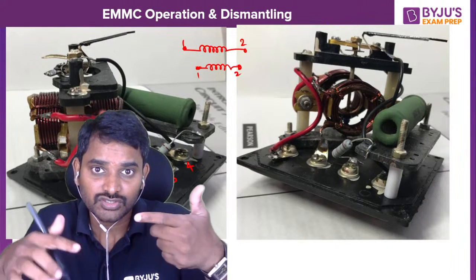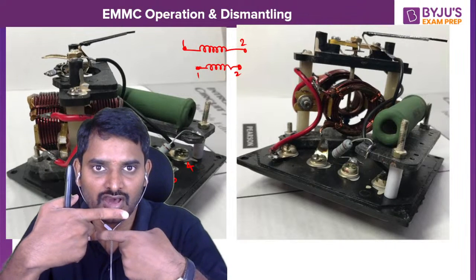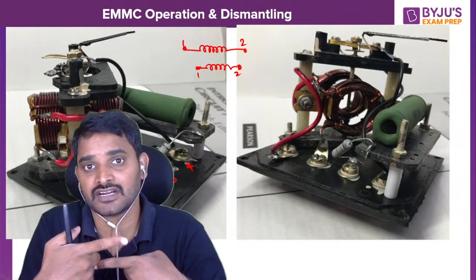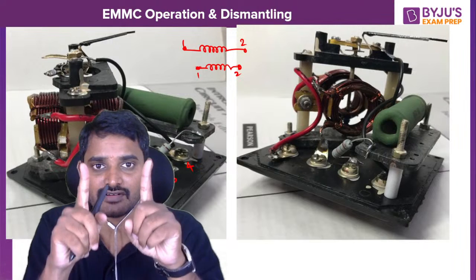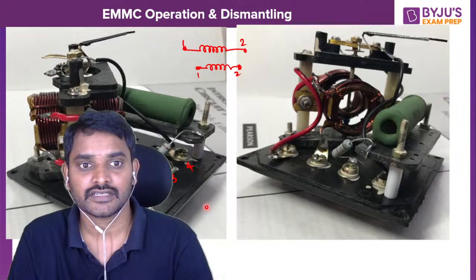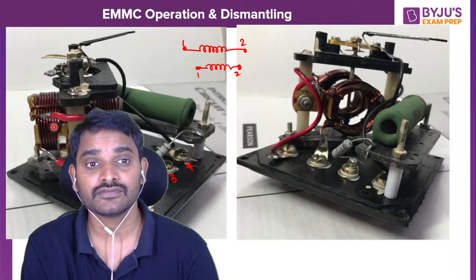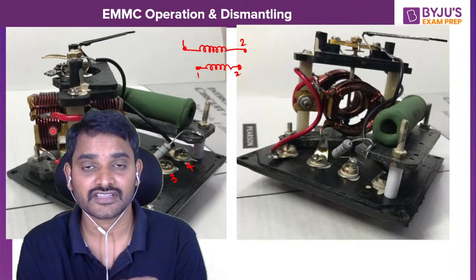On the wattmeter, you will be having some steel terminals. If you connect them in a horizontal manner, the current coil will be in one connection. If you connect them in a vertical manner, the current coil will be in another connection. Okay, all right. Those will give you the range extension for the current coils.